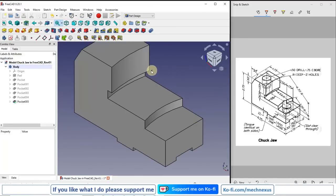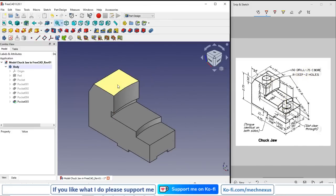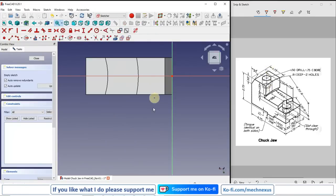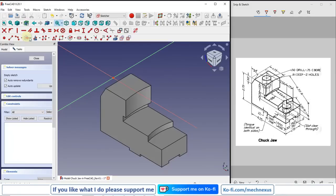And now here we will make this counter bore holes here. So first I will select this face and I will say sketch, and now on this face I will draw a circle. So we can see that 0.5 is a drill and 0.75 counter bore with the depth of 0.81 deep and two holes. This means that this hole and this hole is the same.